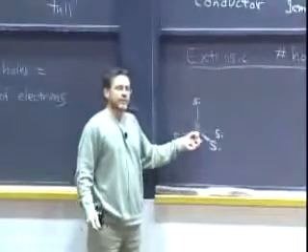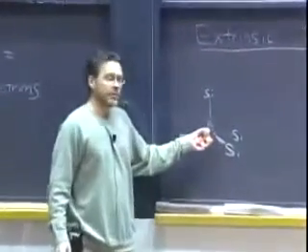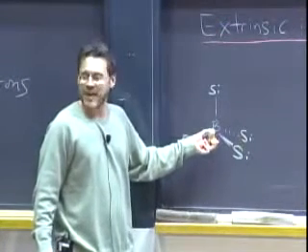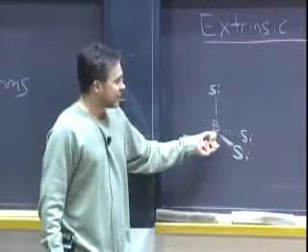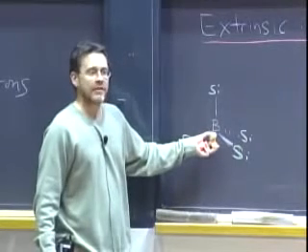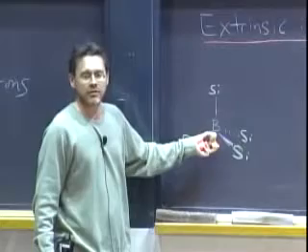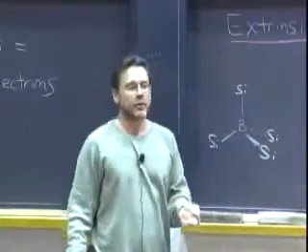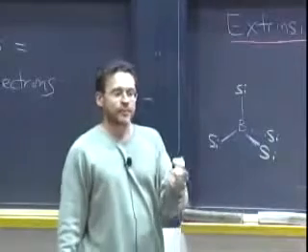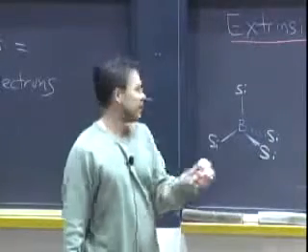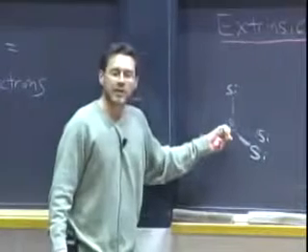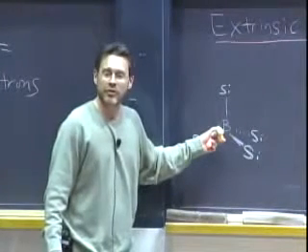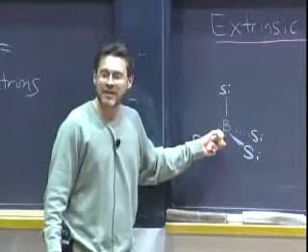But what if we have synthesized our silicon with a little bit of boron impurity? Okay? If we do that, then boron goes into a position in the crystal lattice that is normally occupied by silicon. So boron finds itself surrounded by 4 silicons, each of which wishes to donate an electron to the boron to form an electron pair bond, but boron only has 3 of the needed 4 electrons to make those 4 2-electron bonds and to generate the octet, right?